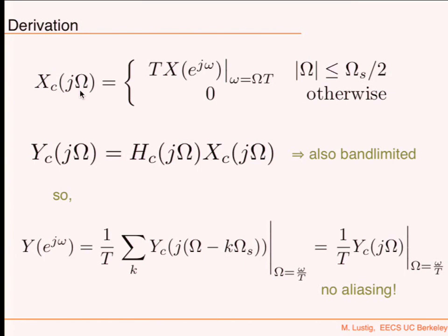That part is going to basically become a band-limited continuous time signal. Something that is discrete, I can describe it using a discrete time Fourier transform from minus pi to pi. That will go and become a continuous time signal from minus omega s over 2 to omega s over 2, band limited. Okay? So this is what it's going to become. It's actually this, right? And we multiply by capital T to compensate for the scaling.